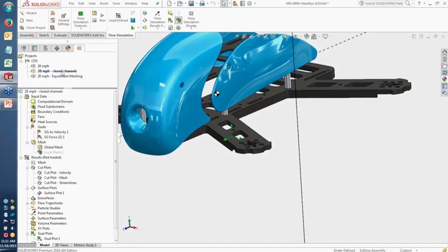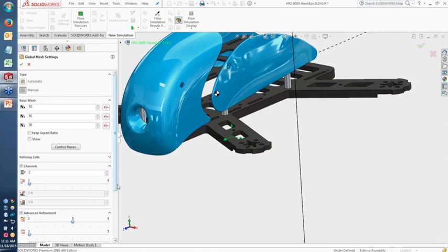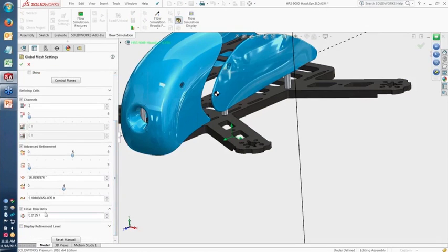This is another project which I cloned. And by going into the mesh settings here and simply checking that box, the close thin slots box, I type in the height of the slot that I want to close off, and it'll automatically go in, and when it generates the mesh, it will detect the size of those slots, and it will basically fill in the slot by turning off that cell in the mesh.